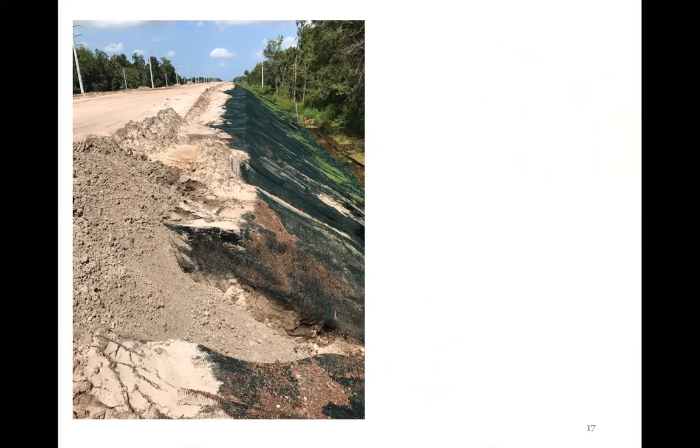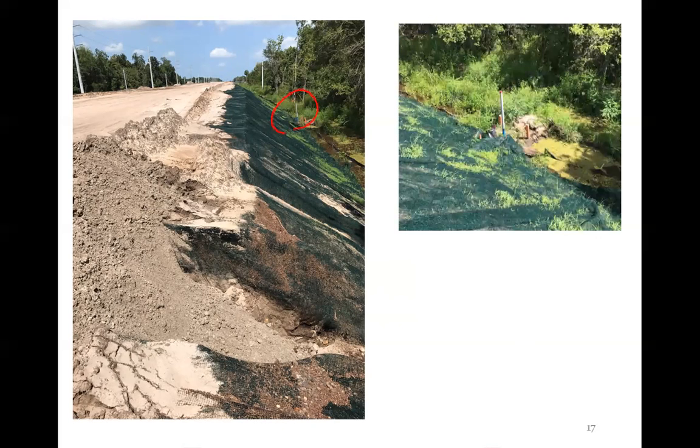And we had to go out every day or twice a week and record settlement, record piezometers. And then we also had inclinometers. You can't really see in this picture, but here is one of those inclinometer tubes, and zooming in, that whole site had settled so much that to get the inclinometer probe into the top of the tube, it was 6 feet above us. So we didn't want to change that tube because we knew the elevation of that tube. So we somehow had to stand on shoulders and get the inclinometer probe at the top because the ground surface had settled so much.